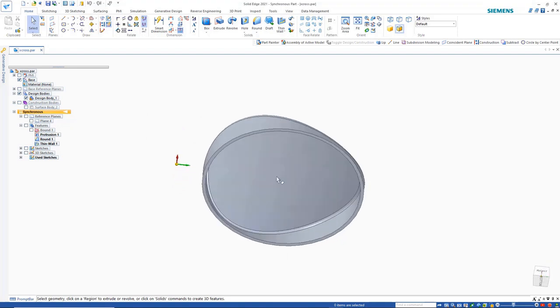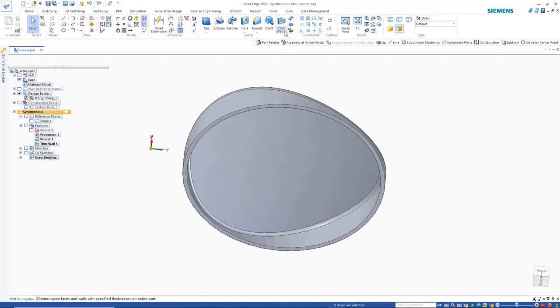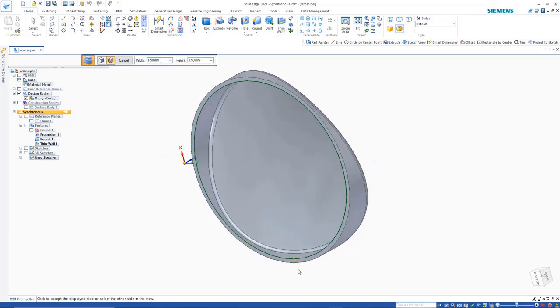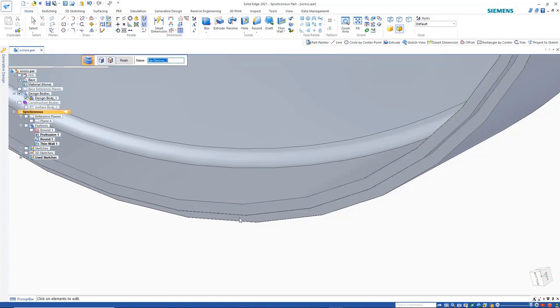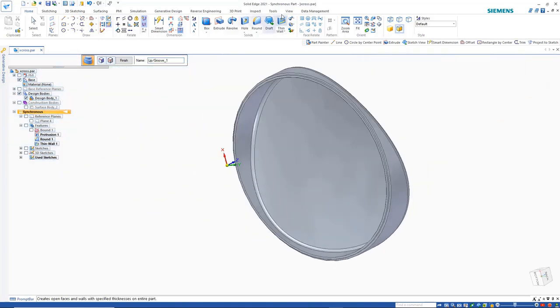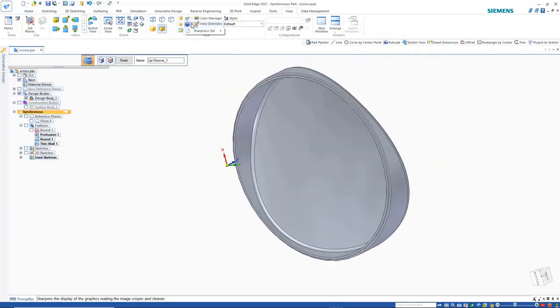Now the next thing I'd like to do is add a lip. So this can connect to the bottom. So I go to the lip command, identify this inside curve, green check mark. Sometimes this can be hard to see, but I'm going to zoom in here, this little triangle, and place that lip right there at 1.5 and 1.5. Just improve the sharpness, finer display.